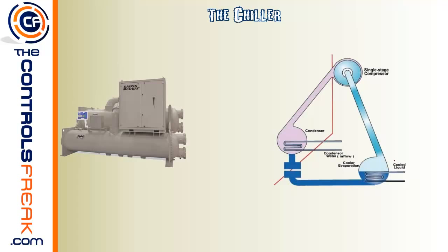One other thing to note about chillers is that in these barrels that you see here, there's many different bolts that come across here that seal up the 2 ends of this barrel. Inside the main portion of this barrel, these water lines that you see here are actually long tubes that run the full length of the barrels. And so if you ever hear of somebody saying they were changing out tubes or they have dead tubes in the barrels and so forth, these are those tubes, and there's many of them.